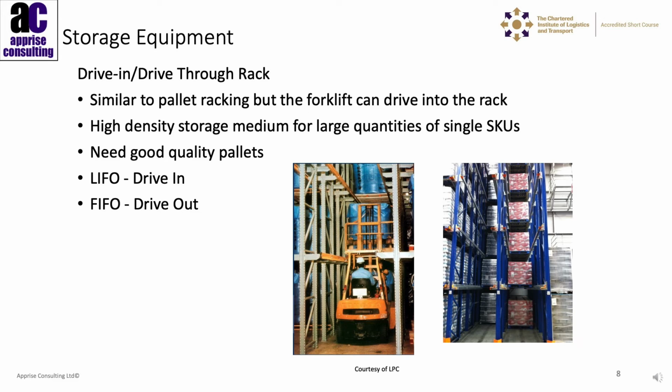However, we then lose the capability of infilling those locations until we've cleared out all of the other pallets. So it's very much a last in, first out operation. We also need good quality pallets, because as they're resting on the load support rails, then there is always a possibility of the pallet actually collapsing within the rack itself.